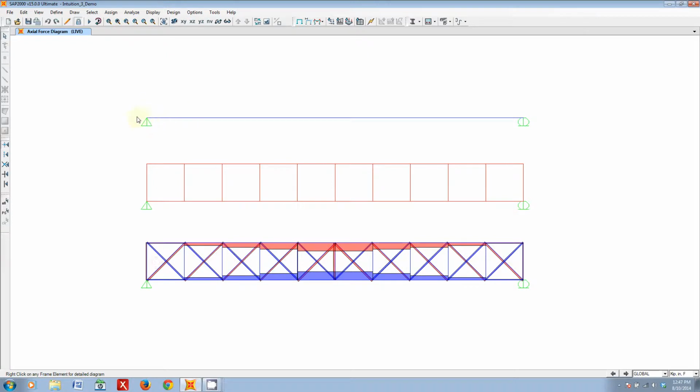And then remember how we transition from negative shear into positive shear right here on the right half portion? Notice how the tensile tendons are pointing down, going this way, and the compressive cords go up like this. Well, that's pretty much true for this whole left half portion until we get to the right half side of the bridge where it flips. Now our compressive tendons are going down and our tensile tendons are going up. And it remains constant on that side of the bridge as well. So, interesting. Our tendons carry the equivalent shear force carried by a beam.